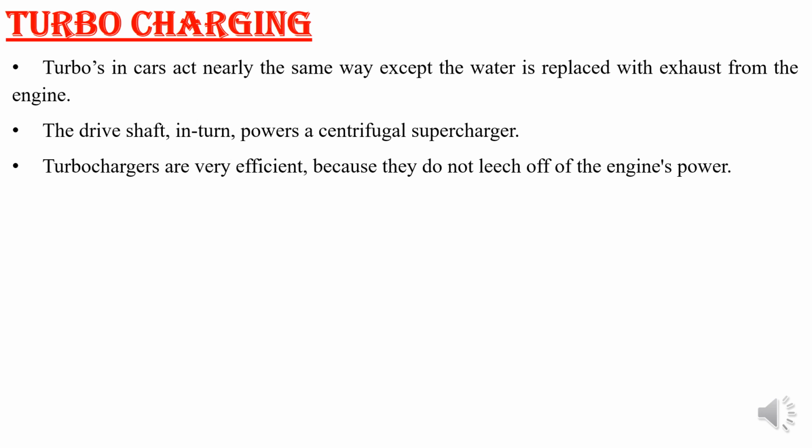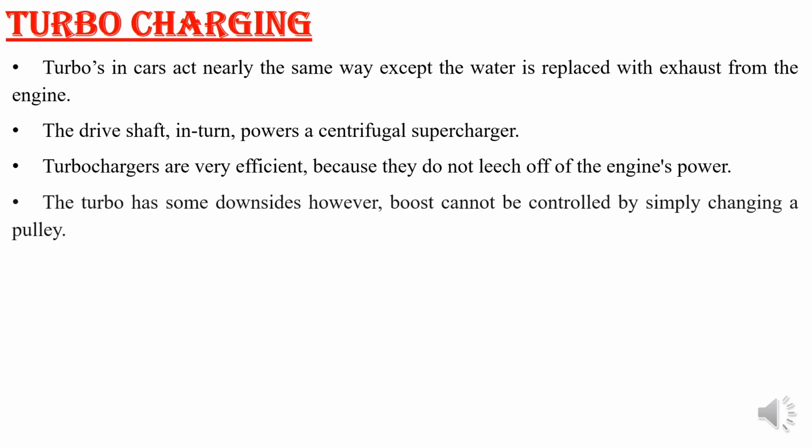That higher pressure exhaust energy comes and hits the turbine blades, so that energy is utilized by the turbine and the turbine blades rotate. The turbine is coupled to your compressor, so your compressor is given power from your turbine.